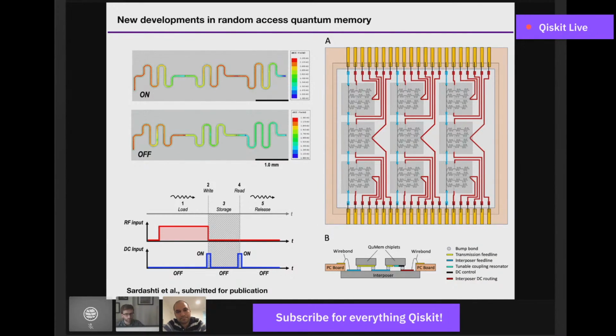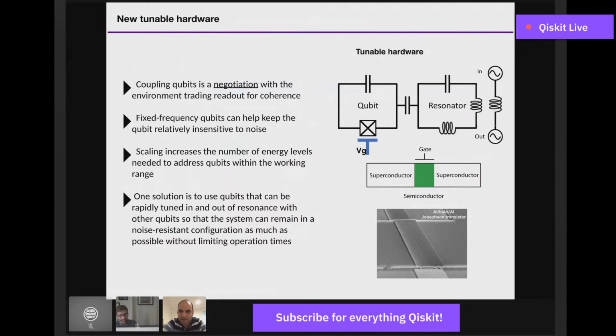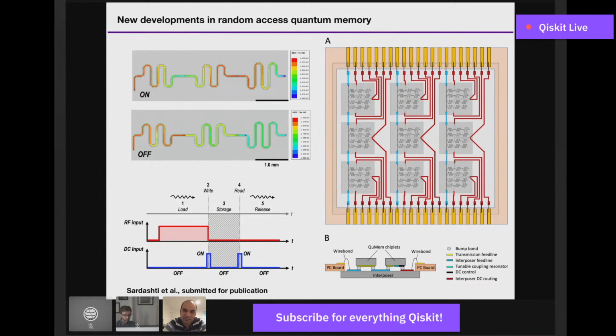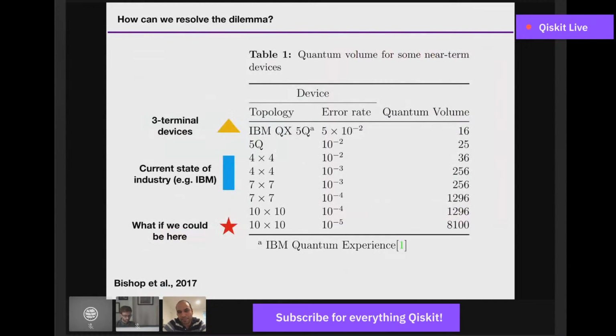Very cool. Yeah. So it's basically a switch. And the nice thing about this is, in the superconducting world, the squids were always the tunable circuits, right? And for a squid, you need some current to tune the magnetic field inside the squid, right? Here, I have just the gate voltage. Let me just go back for a second. Here, you will see that the gate voltage on the transistor never draws current into it, right? Basically, there is a dielectric that always separates the gate from the semiconductor. So the current is zero. You're applying some voltage, so the power that is consumed on that qubit or device is practically zero, right? It's zero times voltage, which is zero. And because it's voltage, you can operate it extremely fast with the RF electronics that we already have in the lab. So that's one way.